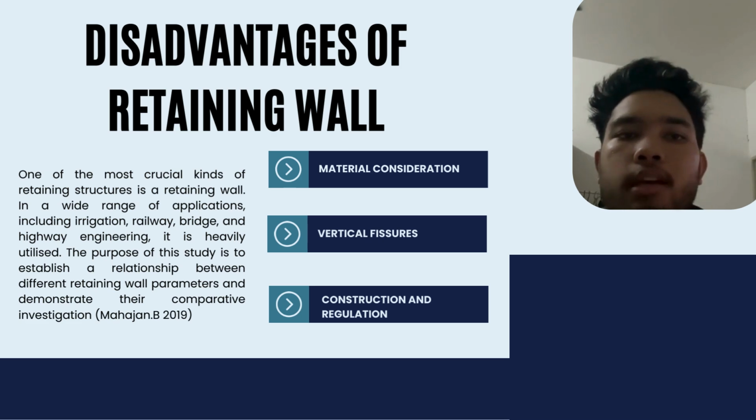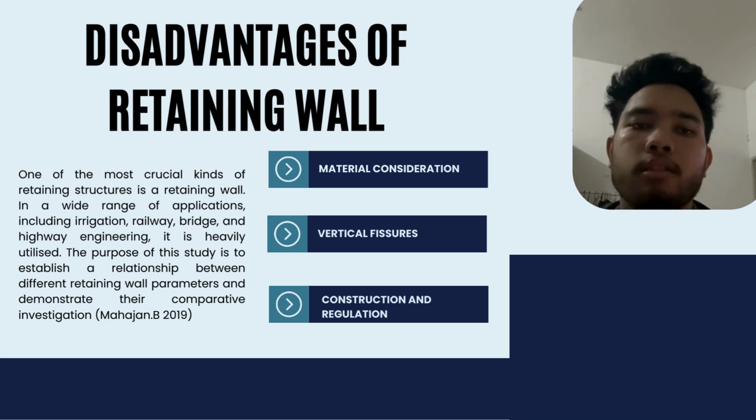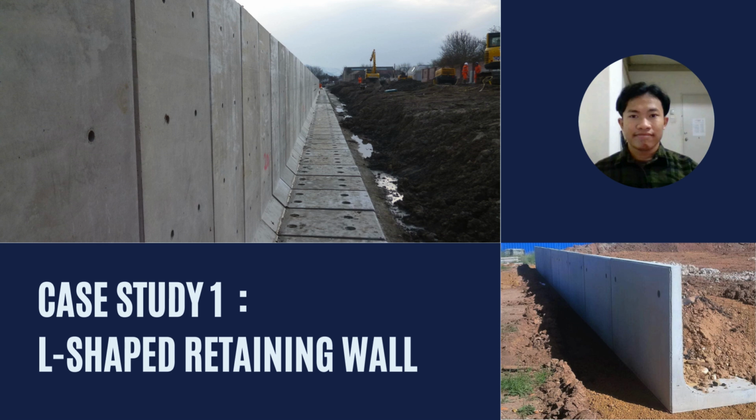If the wall is higher than 1 meter close to a road or walkway, or higher than 2 meters elsewhere, planning permission is needed. Independent freestanding retaining walls might not need to comply with the building regulations, but all structures need to be structurally sound and well maintained.